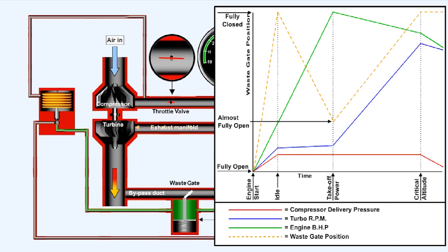From now on in the climb, the outlet pressure of the compressor will fall, and the inlet manifold pressure and engine power output will fall in sympathy. Of course, the engine power output will have been decreasing with every foot of the climb from the moment of takeoff. This is typical of a turbocharged engine, but as we saw earlier, after critical altitude, the rate of decrease gets greater, approximating that of a normally aspirated engine.